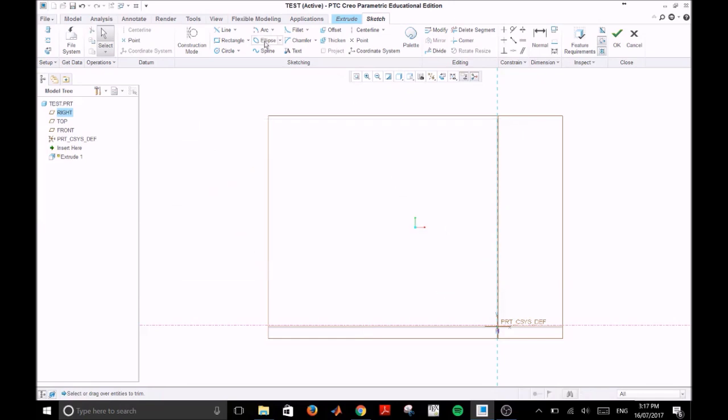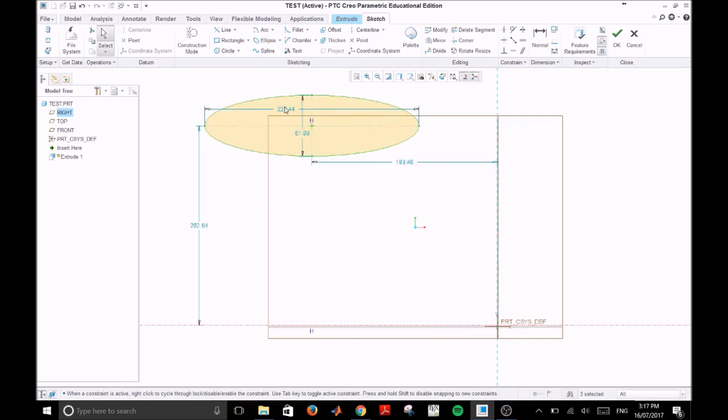and have a look at the ellipse tool. We can specify our outer extremities and then a thickness. Creo gives us these default weak dimensions, which we can later change. We can also use the spline tool. In this tool, the user specifies a series of points. This can be quite a complex tool to control within Creo and is rarely used for a lot of these applications.